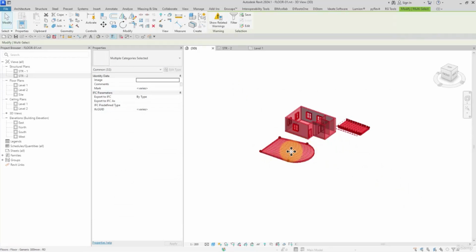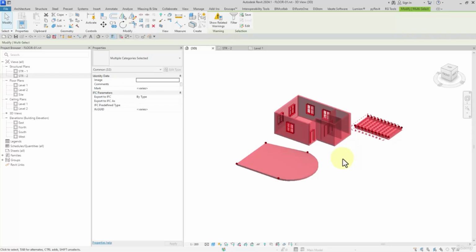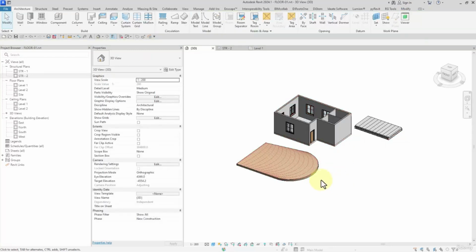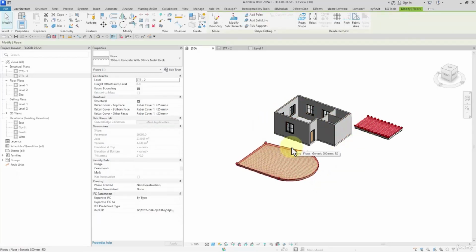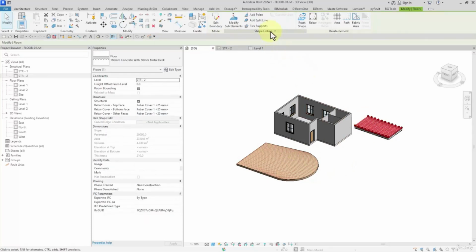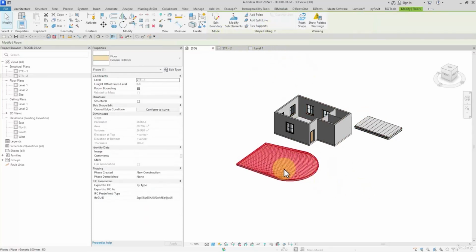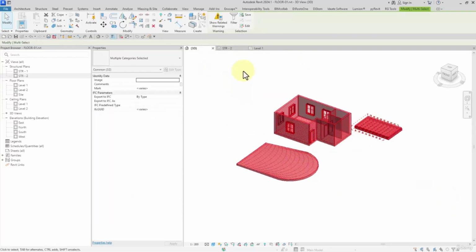If we select these floors, as you can see, the points here are visible since we have edited them once, and sometimes it is confusing and also annoying, especially in large scale projects. So I don't want them to be shown selected. I mean, here we can uncheck preview points. Then, if we select these elements again, the points and the edges are not visible anymore.